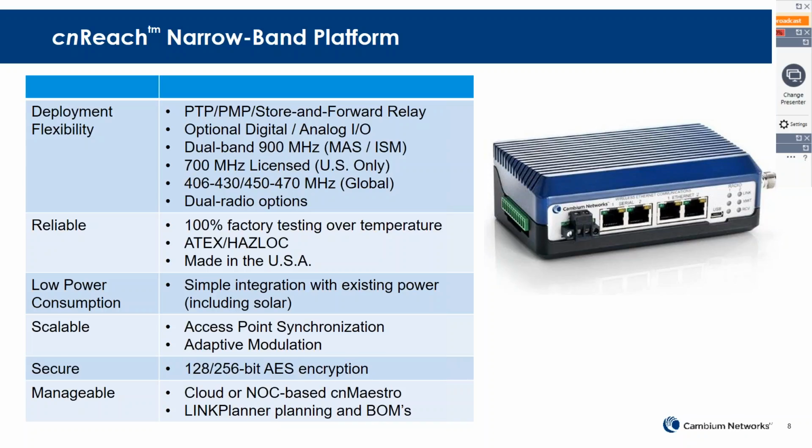You can use any Modbus TCP master to poll the radio to get the things reading, and you can even send Modbus TCP control messages. Say, for example, you can send a control message to shut down a relay pump, or power up a pump, things like that.